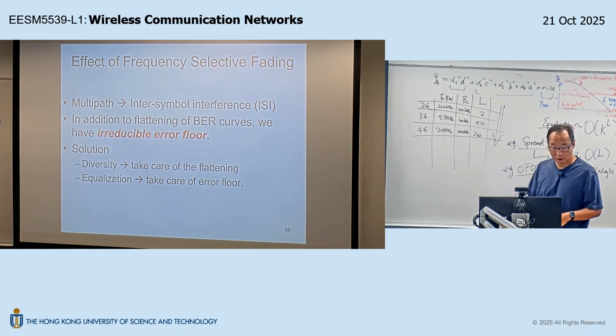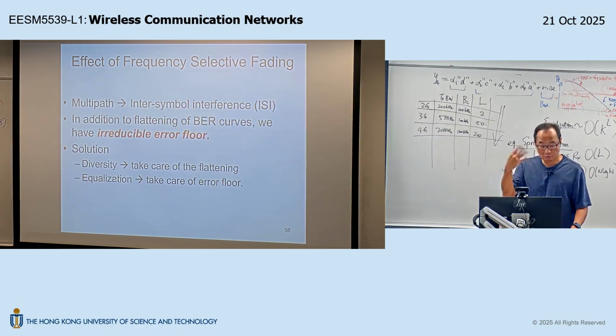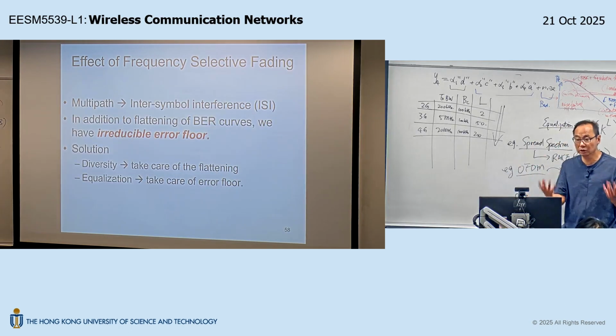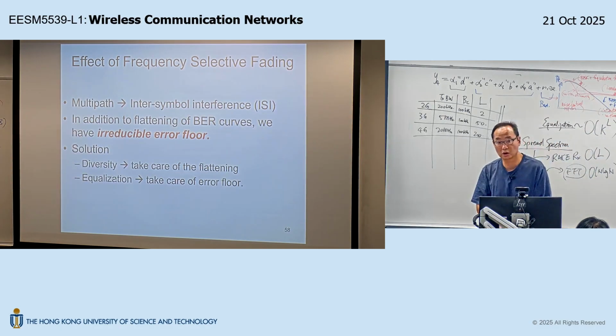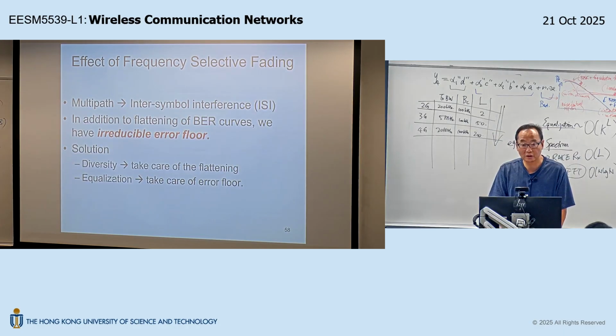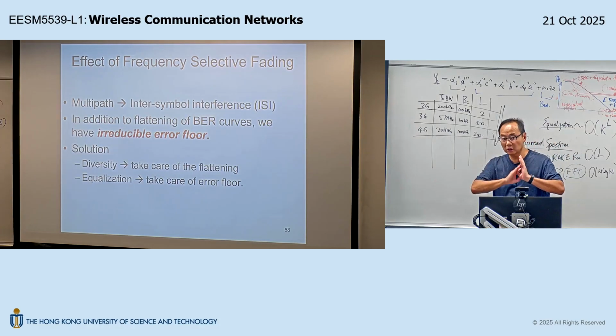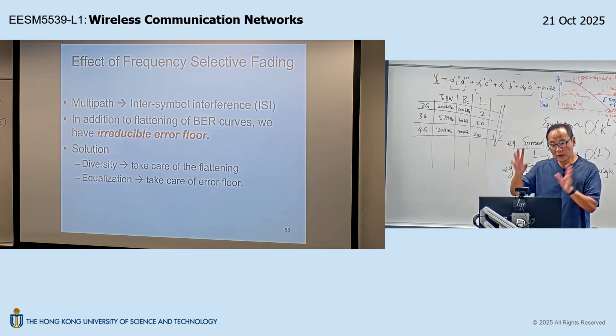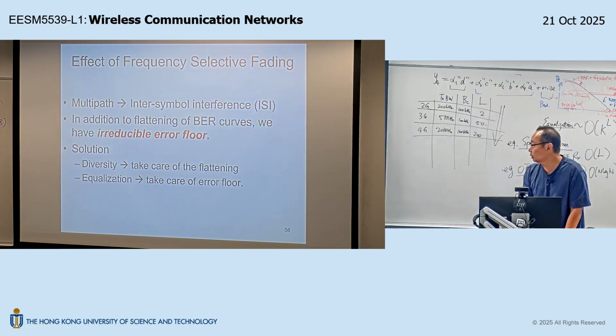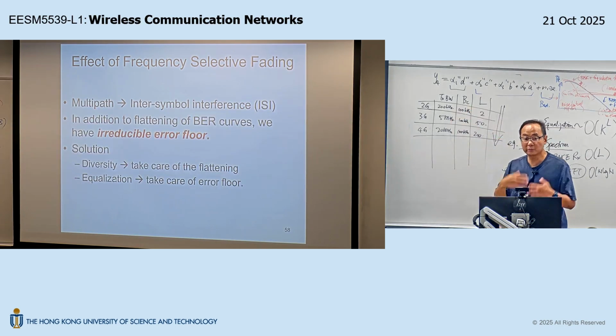In 5G, if you work in this area, one of the topics is called waveform design. It's also a very popular research topic. Waveform design, again, is designing some built-in structure that can be exploited by the receiver to overcome these kinds of frequency selective fading problems, the two-tap trouble. So of course, as I say, you should not dump all the equalization burden to the receiver. If you do it this way, the receiver will end up having exponential complexity of equalization, and that cannot scale. So the typical solution, especially as you go down the generations, is that the transmitter plays a very important role.